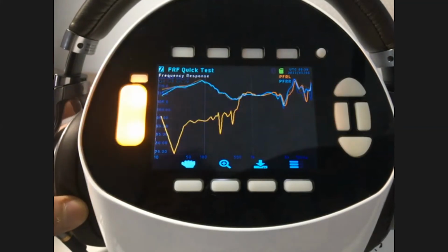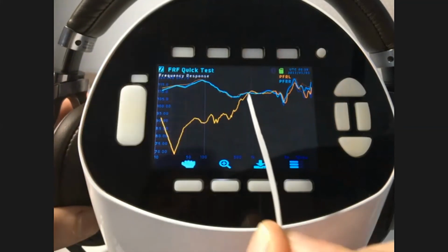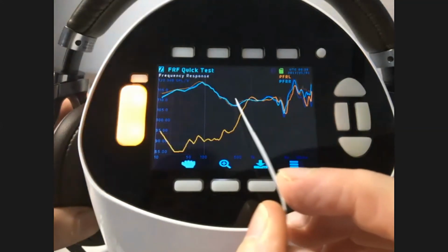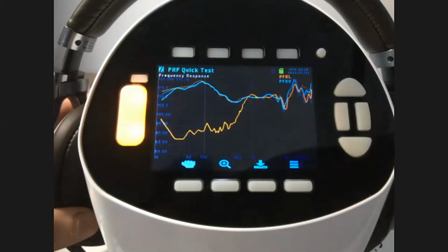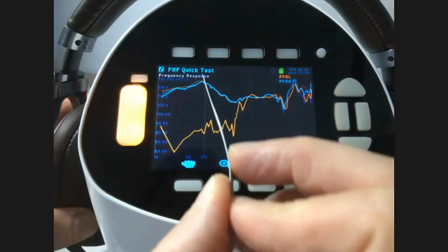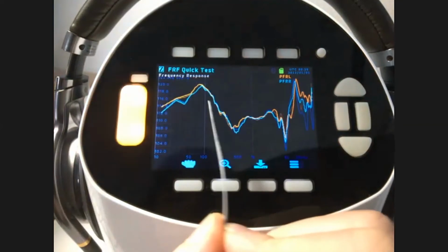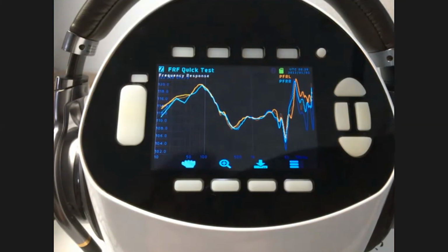If I just turn it into a speaker, removing the ear pad seal, you can see now it's just operating like a speaker. So that tuning frequency can't really go higher than that. It's a natural speaker frequency. And at the lower end, you can't really go lower than that peak. So you have a limited range where you can move that notch frequency up and down before it stops having an effect because other things take over.